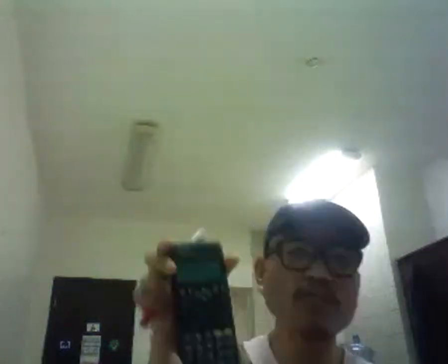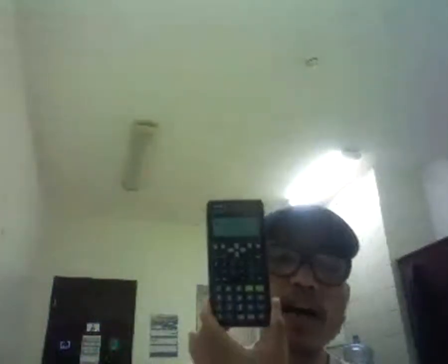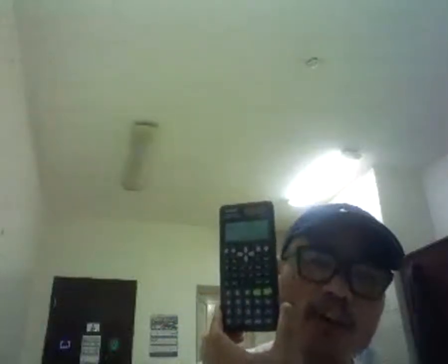That gives 3,062, closer to 4,000. It is in the transition stage, not yet laminar, right? The transition flow is 2,100 to 4,000 for the Reynolds number, but I obtained 3,062. This is still the transition stage going to turbulent. So it's still wrong if you add all the lengths of diameter A and diameter B.